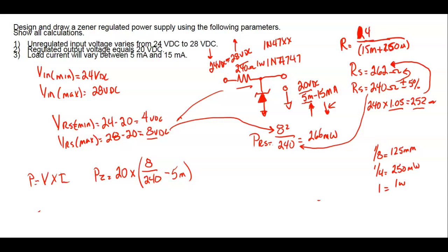So Zener current varies opposite of the load current, but it varies in the same direction as the input voltage. So we're trying to figure out when the current flow through the Zener would be maximum, right? So what did we do here? We calculated the current in the circuit, and then we use this to calculate the current in the Zener.